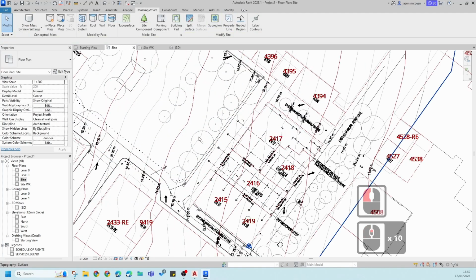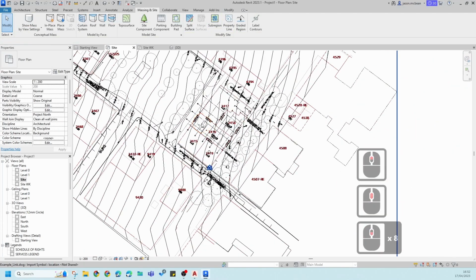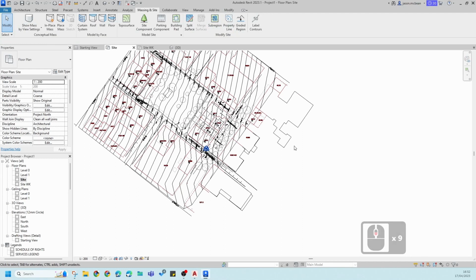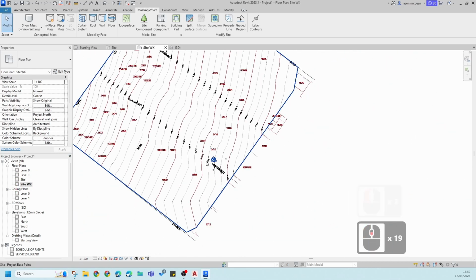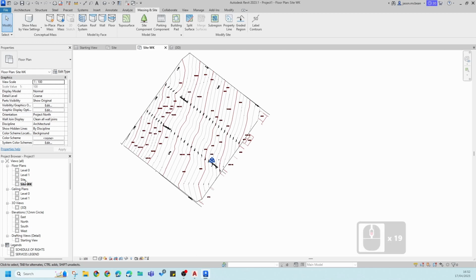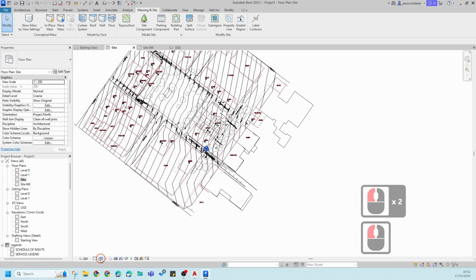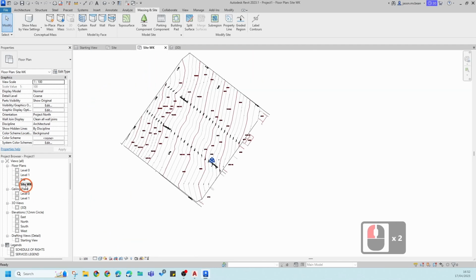Okay, so this is just one thing that you need to remember about Revit, because the contour surface goes up, and your levels that it cuts through the building can only be viewed in ranges, view ranges. So that's something that we'll get to once you start doing your building. Okay, great. But for the time being, in site working, in this view, we can leave everything as hidden line or shaded. That's totally up to you for this exercise.